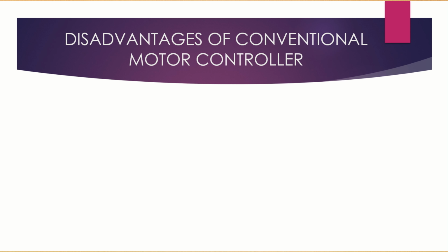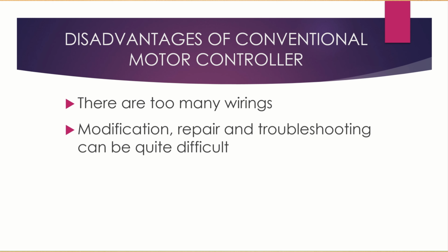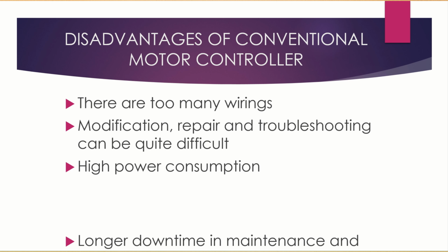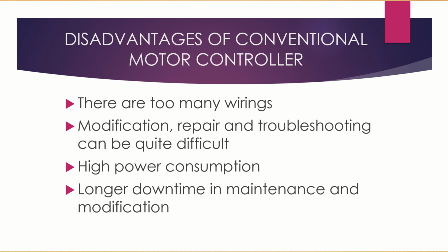Here are the disadvantages of the conventional motor controller. First, in a conventional motor controller, there are too many wirings. Modification, repair, and troubleshooting can be quite difficult. Also, there is a high power consumption in the conventional motor controller, and then longer downtime and maintenance and modification.